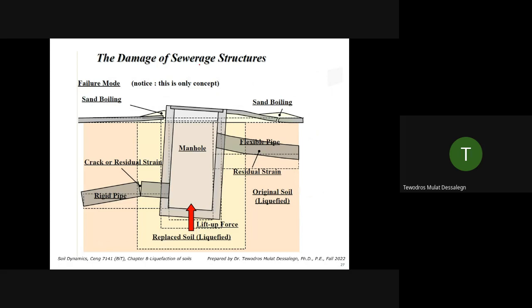The damaged sewerage structures or buried structures. It's a very interesting phenomenon for buried structures. Those sewer pipes or even tunnels. Tunnels may be deeper, but if there is a shallow depth and if liquefaction occurs, what happens? When liquefaction happens, there is high water pressure underneath, right? So it lifts up the tank. The water tries to go up, but there is a solid concrete, so it pushes it up. And it breaks the pipes, concrete pipes nearby. And you'll see this buried structure coming out to the ground surface.